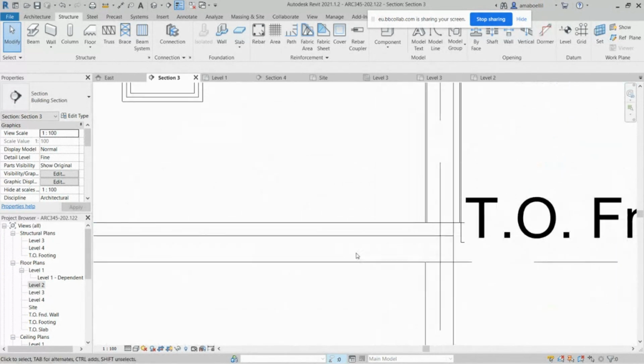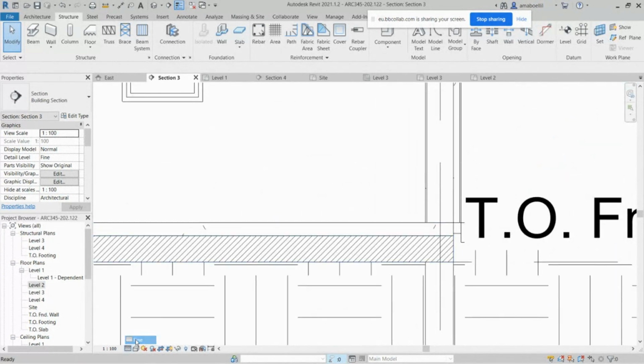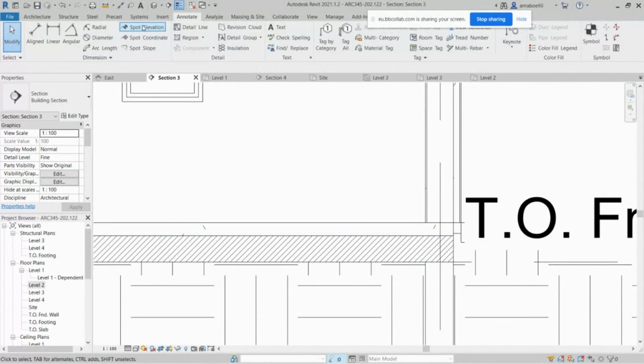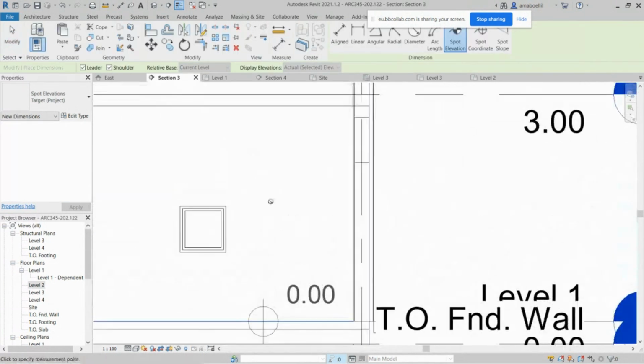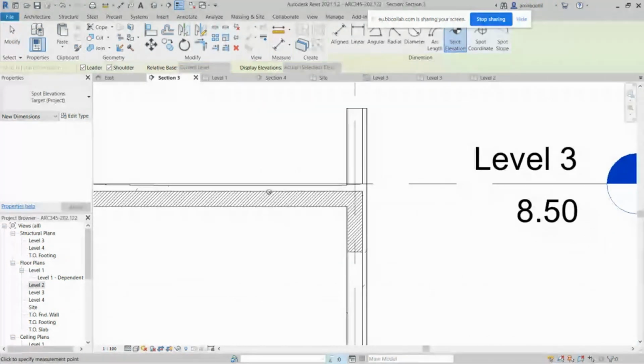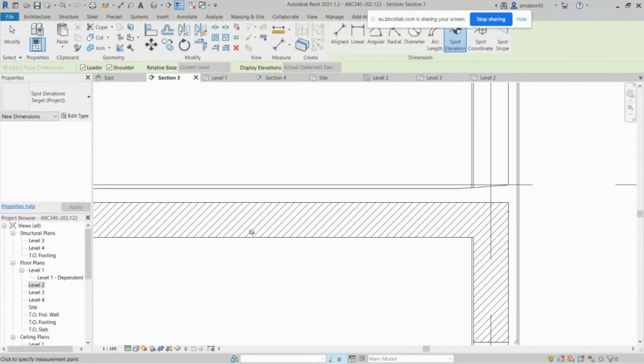Like if I have my flooring system like this, and I have my slab like this, I can still do this, and I will show you one of the reasons when we annotate to different levels. Here it senses that level as 0, 0. If I go up in here, it senses the bottom here as 8.2. It does not sense what is in between. It does not sense whether I'm on the top of the slab or not.